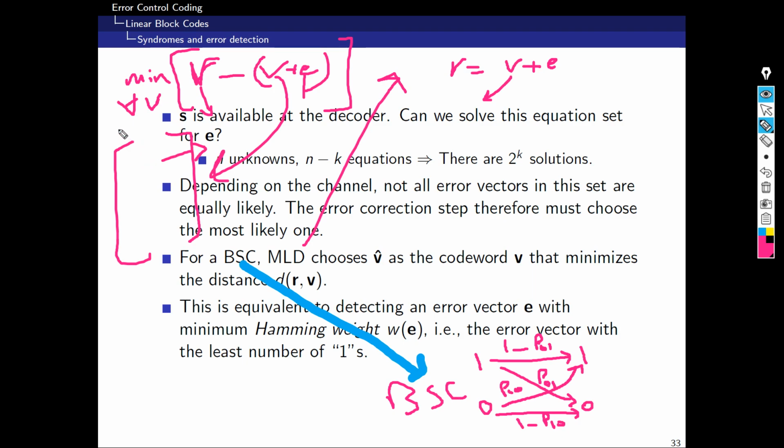So you define a for loop and you go over all of them one by one. The one that gives you the minimum result here, that reduces this value to the minimum, you detect as the code word that the transmitter used to represent the message. And from here you detect that this was the code word. This process of detection, we call it maximum likelihood.